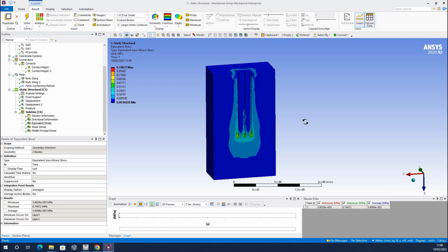The limitations of this model, of course, are that the model is linear elastic and isotropic for the piles and for the 2 layers of soils, but it's a valid model that you will find in the literature, and there are many classical methods that use elastic approximation to solve the problems. We are going to add more complexity in future videos in terms of post-processing, and we're going to talk about a model that can be, for example, orthotropic with different properties in different directions, so no longer isotropic. We can talk about plastic models in the future.